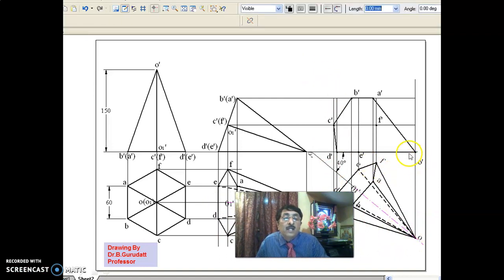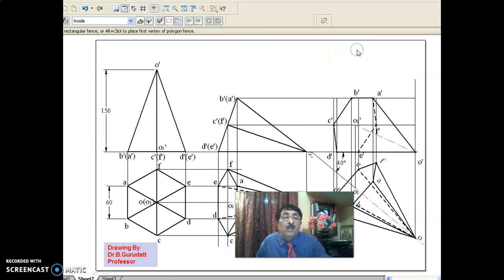Now as you see here it is a triangular surface, 3 edges are here only, 3 here, 4, 5, 6, 7 edges are already over. Since apex is nearer than the base, remaining edges of the base is not seen by the observer. You make it dark dotted. Now you count the edges. It is 3 here, 4, 5, 6, 7, 8, 9 edges are already over.